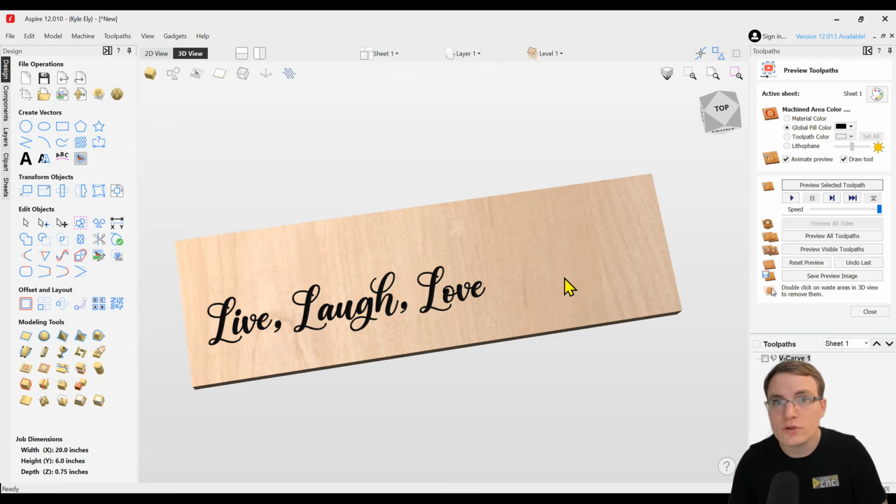Also, if you save your toolpaths outside of Vectric in an earlier step and you made changes like this, make sure you resave those toolpaths again and get rid of those old ones with the wrong G code because of that spelling error that we had. So recalculating toolpaths like this will help you save any mistakes that you possibly may make on your machine. So it's always a good idea to check everything before you save it and make sure everything is correct.